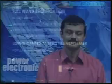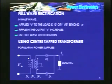Instead, if we connect a diode across the load, beyond pi, this diode connected across the load, which is also known as a freewheeling diode, starts conducting. Now the voltage applied to the load becomes 0, and the current decays slowly. Okay. What was the third point that we discussed?